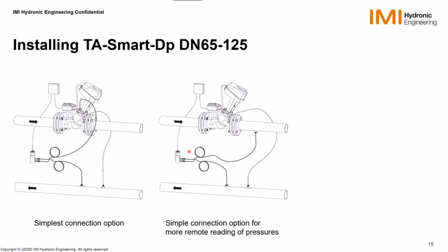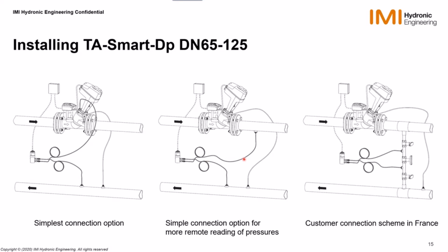That's not so good. If you need even more distance between the supply and the return pipe and with respect to the place of the delta P sensor, you can, of course, extend the capillary pipe with the usual extension kit for capillary pipes as we have for the STAP. And the final connection scheme is this one, similar to what I've shown to you already. And that is being used in France by installers. Good.